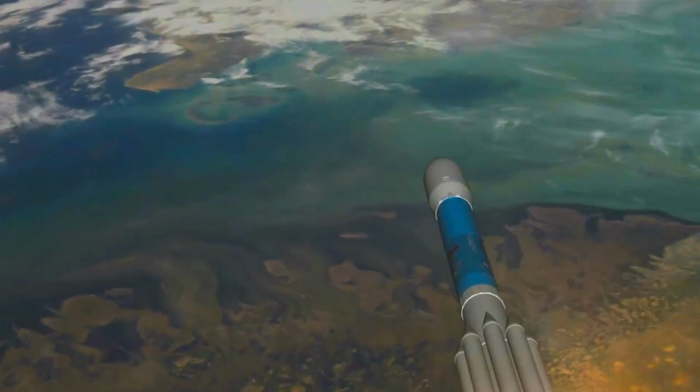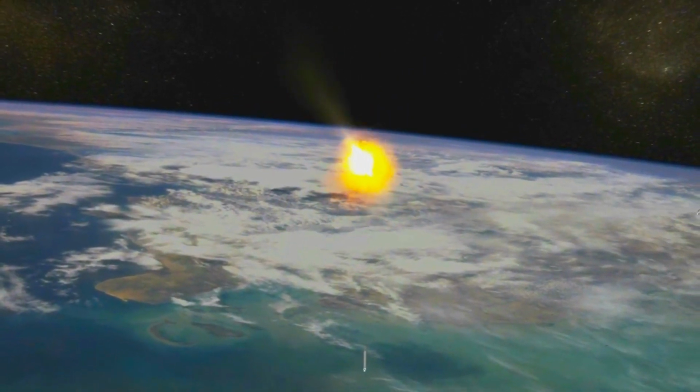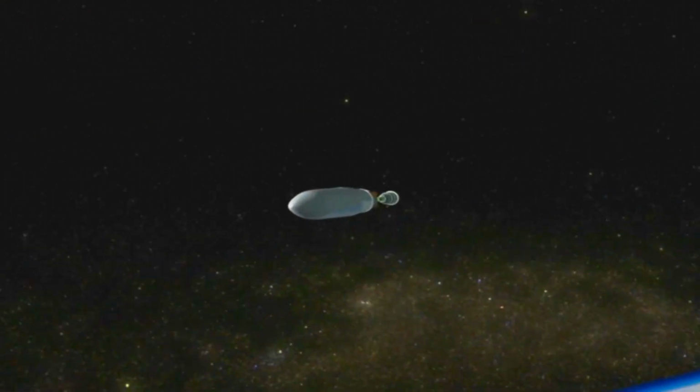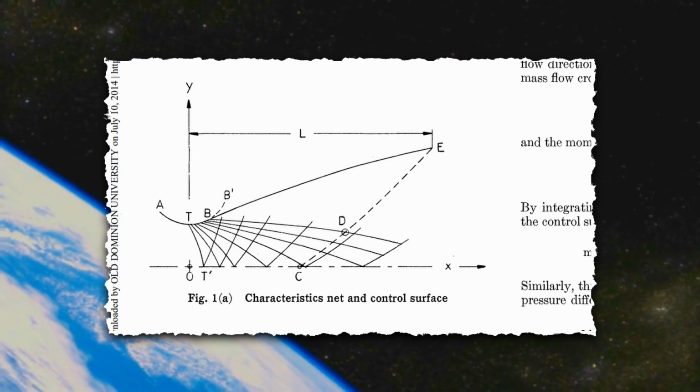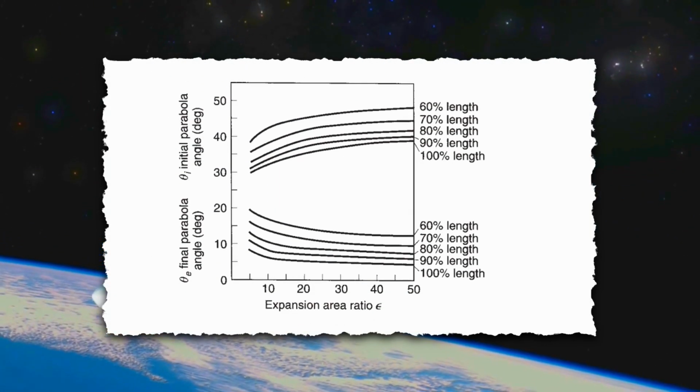ratio. Rao established a method for optimizing thrust by designing the wall contour based on nozzle length, ambient pressure, and flow conditions. This involves the use of isentropic flow assumptions and the method of characteristics to construct the nozzle contour. Angles θN and θE, crucial for this method, are obtained according to the expansion ratio.